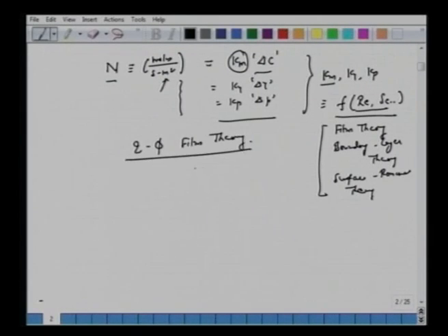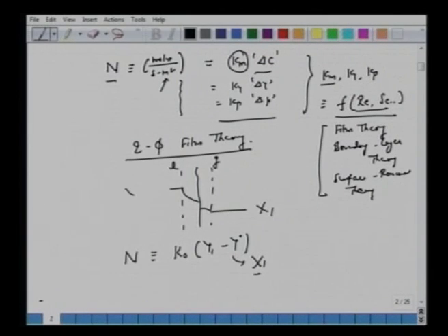So now we are talking of an interface of two different phases, liquid and gas, and then we said we can have two resistances where we have this concentration drop like this. So instead of working on individual film transfer coefficients, we said that we can also write the expressions for flux in terms of overall mass transfer coefficient and two concentrations in the bulk phase. So Y star here would be in equilibrium with, let's say, X1 on the other side. Essentially we have these engineering parameters to estimate this rate.